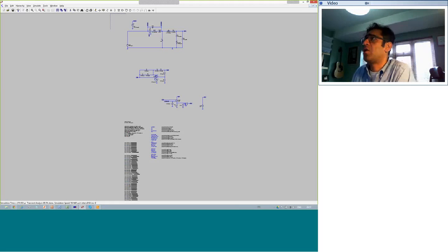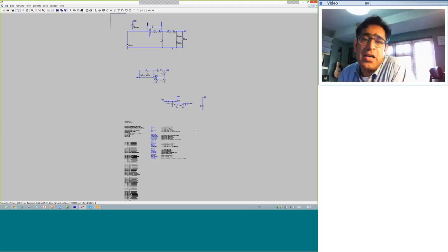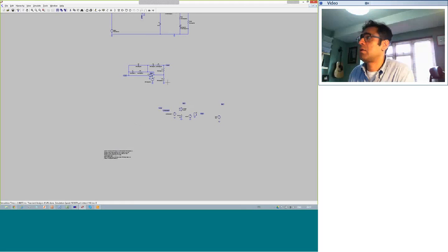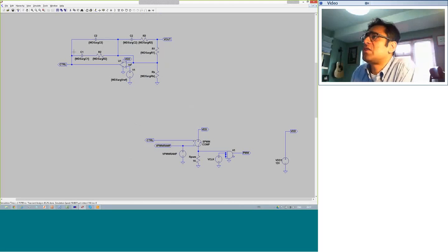And there you go. WDS has automatically generated your buck converter. It has automatically populated all of your component values. So if you've selected 440 microfarads for your output capacitor, that is what is appearing here. If you have selected 30 milliohms for your ESR, that is what is appearing here. The poles and zeros of your compensator you selected, WDS has automatically populated that.